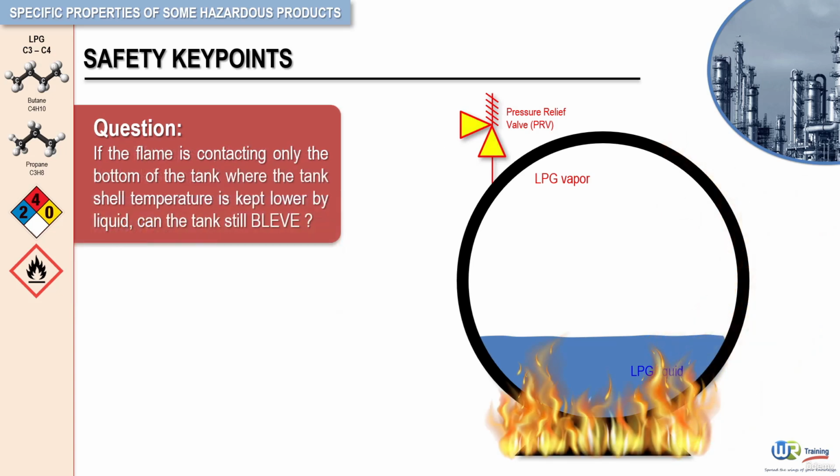Now, if the flame is contacting only the bottom of the tank, where the tank shell temperature is kept lower by the liquid, can the tank still BLEVE? The answer is yes, but it may take longer to happen.